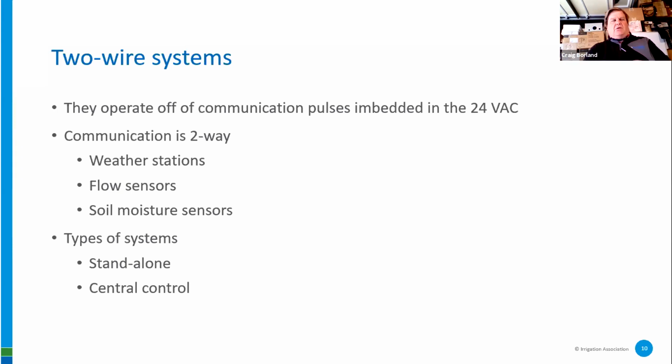And I can adjust my irrigation schedule to modify or account for that moisture differential out in the field. So they're not just for turning on zone valves. You can hook them up to these devices and more coming. Also, they can be a single solitary standalone system, where I want this clock to operate this specific park, I want this clock to work this specific commercial building, I want this clock to work this specific right of way.